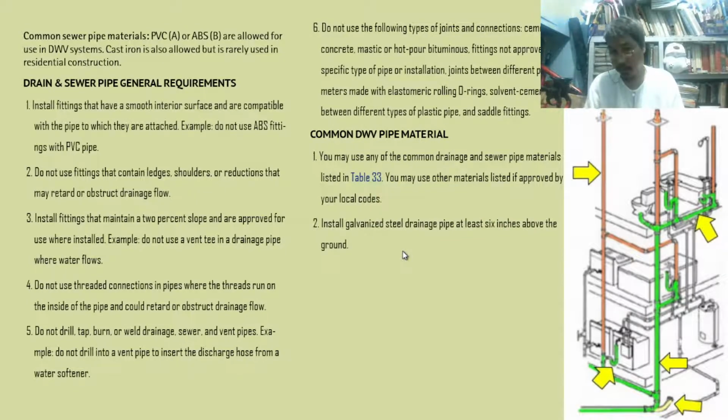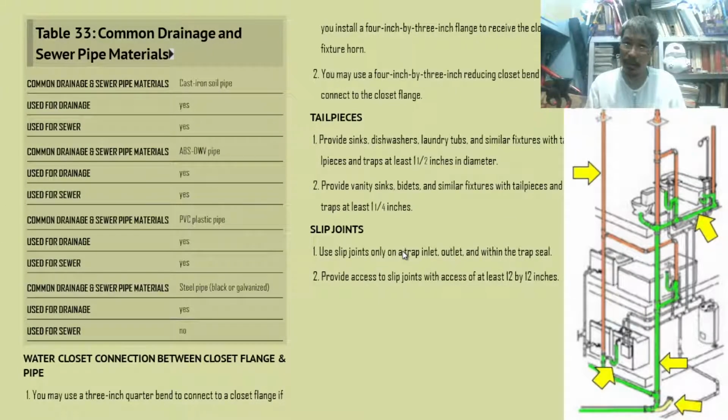A galvanized surface is only effective against oxygen or oxidation, to prevent corrosion of the material. But if it reacts to other minerals and elements in the ground, it would deteriorate its properties. So this is the listing of approved materials for drainage and sewer pipe.